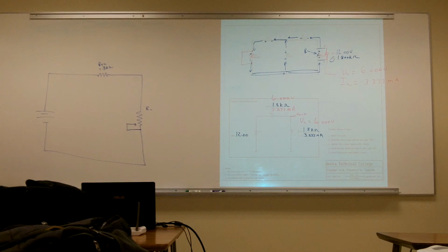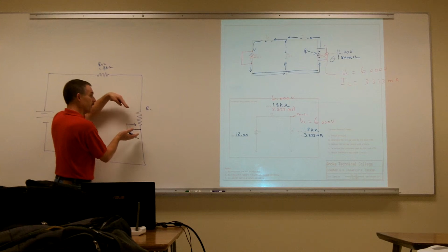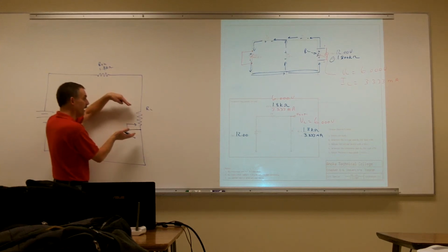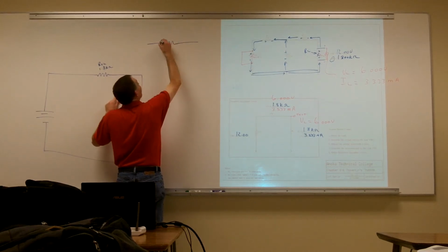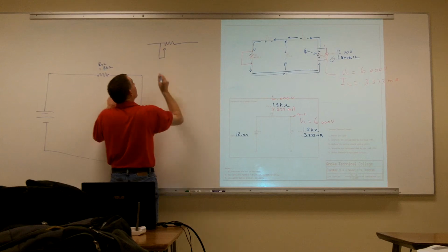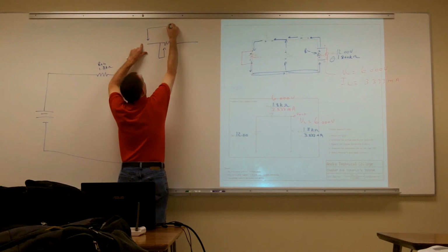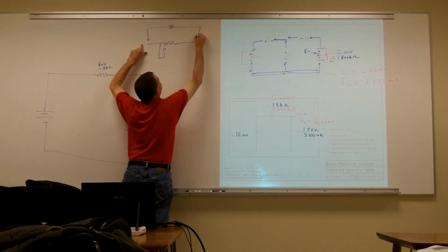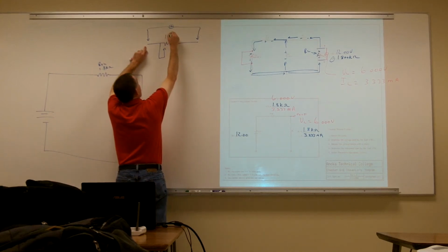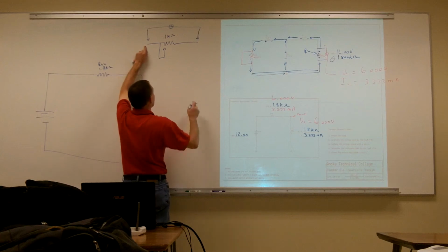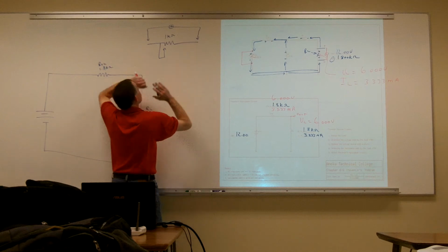So if there's somewhere in the lab asking for a certain value of a resistor and you don't have one, we can always configure our potentiometer as a rheostat. If I put an ohm meter across here, and let's say this is a 1 k ohm potentiometer, with my wiper all the way to the left, how much resistance would I measure?